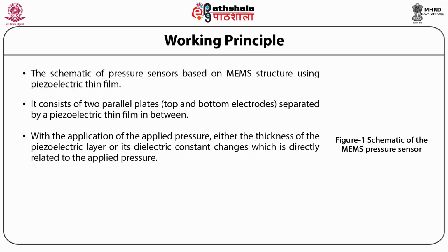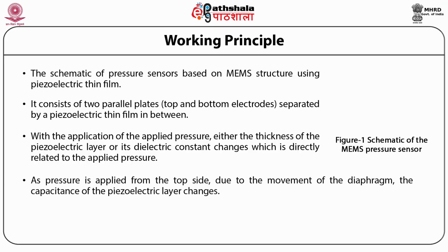The schematic shown in the figure on the left hand side gives the design of the pressure sensor based on change in dielectric constant of the piezoelectric layer on application of pressure. As pressure is applied from the top side, due to the movement of the diaphragm, the capacitance of the piezoelectric layer changes.